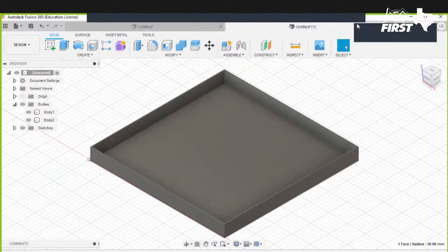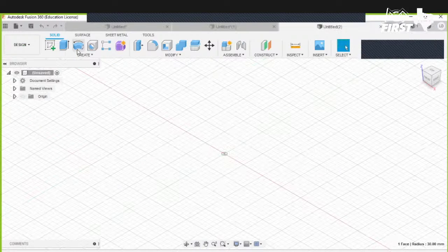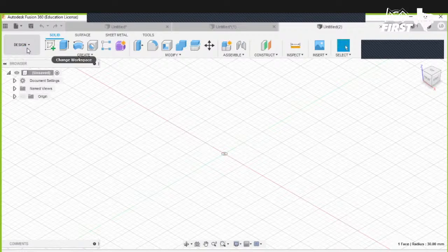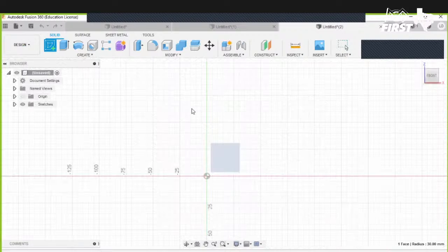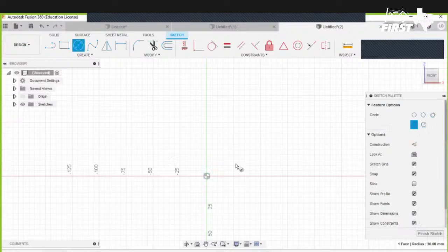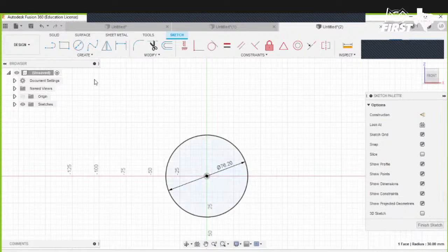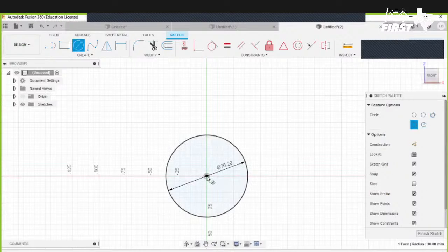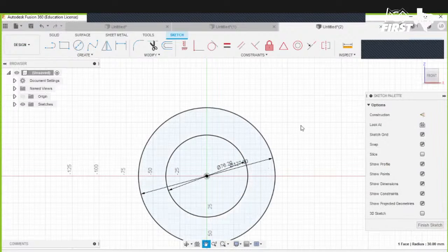What I want to do is open a new sketch, and here we have a whole launching game. So let's go ahead and create the rings. There's 2 ways to do it. We can make a shape of a ring and extrude it out, or, well, we'll cover that for now. So we'll get a shape of the ring. We know that the inside is about 3 inches in inner diameter, and the outer diameter is 5 inches. So there's the beginning of our ring.